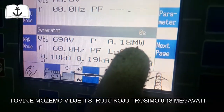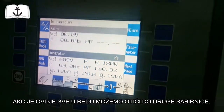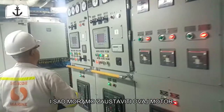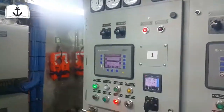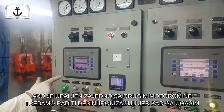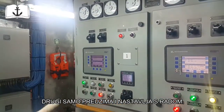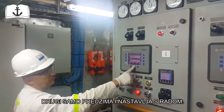It's a 0.18 megawatt consumption. Okay. Yeah. And if everything is okay and we're happy about it, you can go to the other engine. Maybe we will make a blackout. And now we need to stop this engine. So basically, when it's running on board with the other one, you don't need to desynchronize it. I will just cut the power off, and the other engine in the proper factor will take over everything, hopefully.